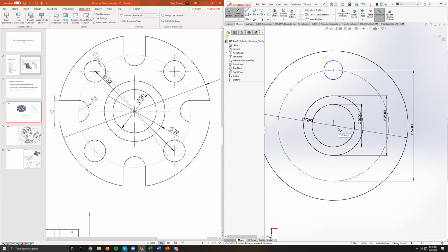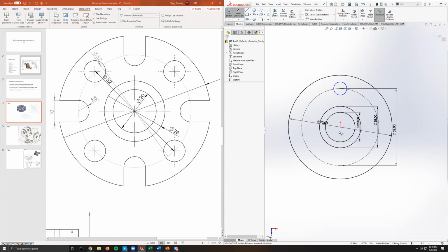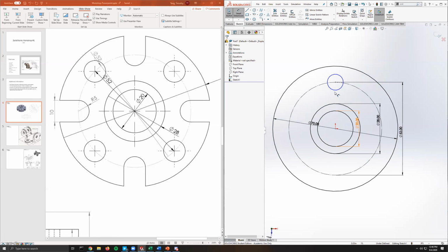Oh yeah, usually it's just personal preference, but in this case I want you guys to start on the origin. Because if you don't, then the centers of your circles are going to be placed everywhere and not locked in one place. Okay. Yeah, okay.